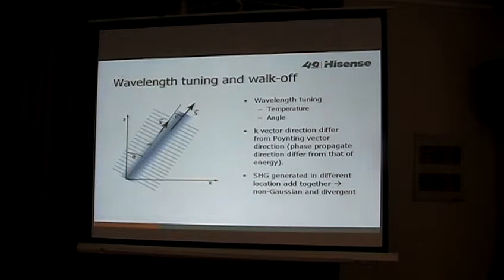But the problem with this scheme is, if we tune the angles, we get the so-called walk-off phenomenon, which means the phase propagation direction is different from the direction of the energy propagation. This has some consequences for device design.